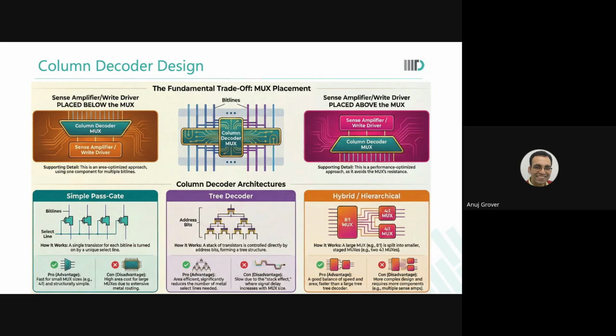But for that particular cell where you are facing a problem, yes, port A is in the read mode. Not exactly reading, it's in a read mode. The word line is on. If it was reading, the precharge would have been off. Even then the problem wasn't there. Are you able to see this?